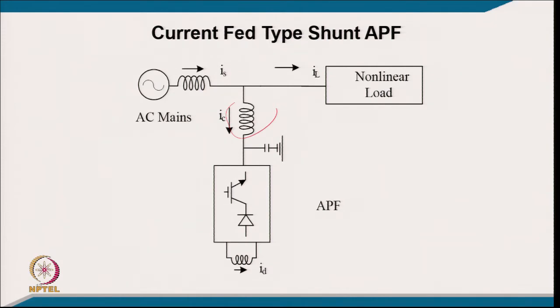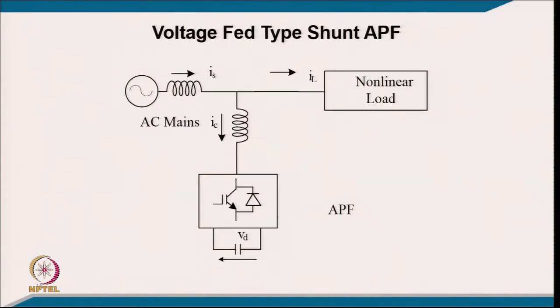Of course, people have initially used it, and you will find a lot of attempts and research publications, even with experimental results, but later on people have gone with the voltage source type, the voltage source inverter fed active shunt filter. Here, in the shunt filter you have a DC link capacitor, which is an electrolytic capacitor, which is cheap, has less losses, and is smaller in size. The voltage source converter or inverter is supported with an IGBT and anti-parallel diode, so it does not require a reverse voltage blocking ability.